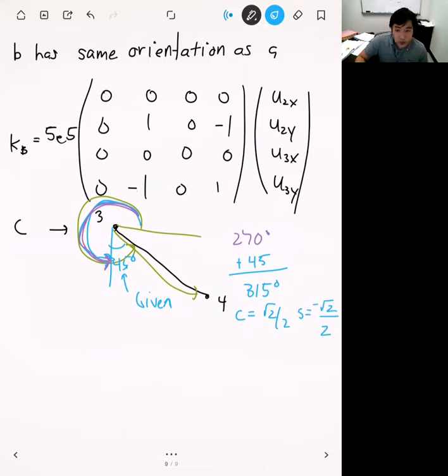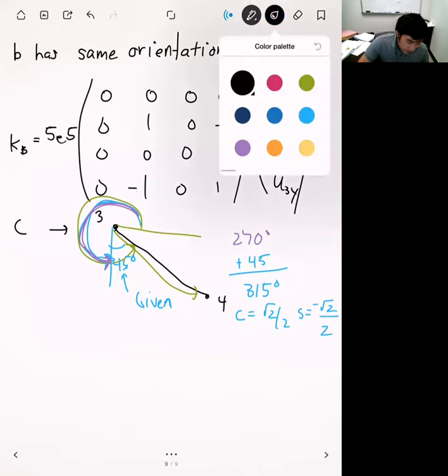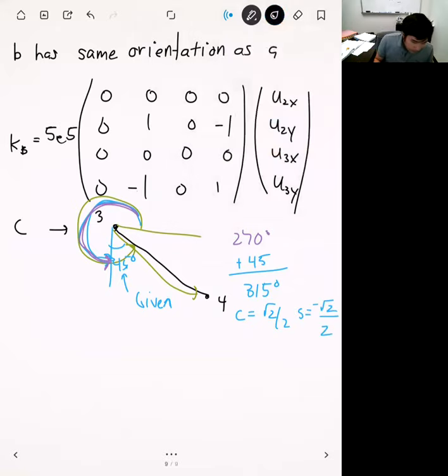Okay. All right. And so let's go ahead and plug that in. We have another EA/L here. Okay. So the length for element C here is longer. And so that's going to modify our effective spring constant. Okay. All right. And so the element stiffness matrix for C is going to be 3.53E5.